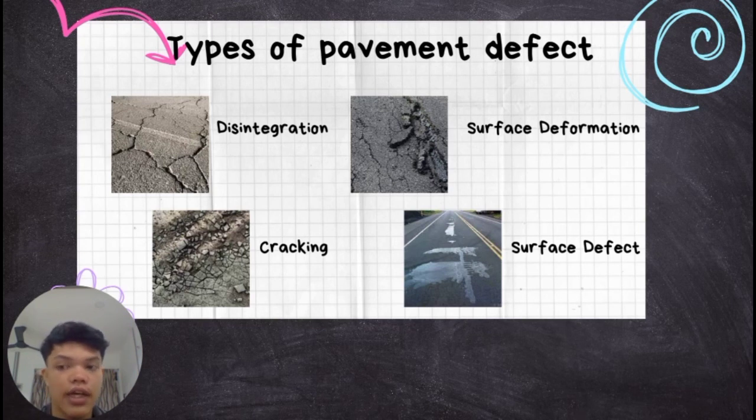On the other side, we have cracking. So, what is causing cracking on the pavement? Basically, it is caused by either repeated loading from traffic or temperature induced cracking. Over time, both types of external factors will cause the surface asphalt layer to crack as well as the subgrade to become weakened in some cases.